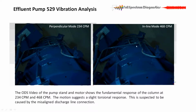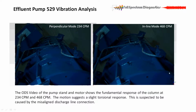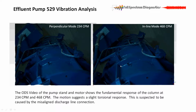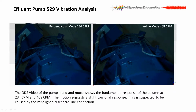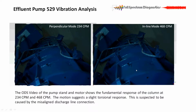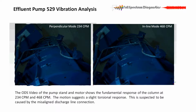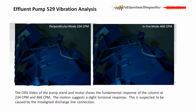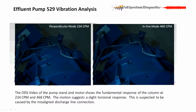This is the inline mode, so a little stiffer, a little higher frequency. And you see a couple of things. There are multiple modes in here, it appears, and we're locking onto a natural frequency, so it's trying to follow the mode shape of the natural frequency. But at the same time, any residual unbalance in the pump looks kind of orbital, like you're orbiting around some point at the end of the motor here. So you get a little bit of twisting in it.